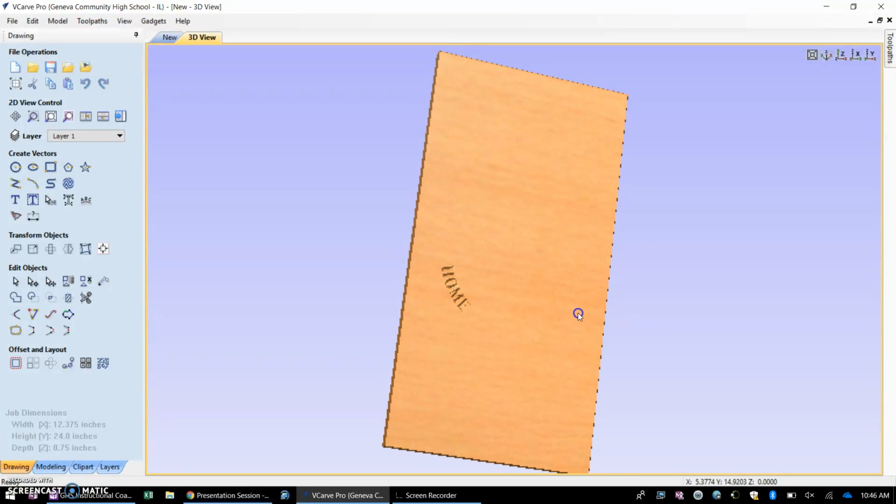Okay, so notice how it's not through because it just doesn't need to cut that deep. If you end up cutting too deep, the software will warn you that you're going to cut too deep. If we cut through the wood and we want to do that on purpose, it'll tell you you're going to cut through. So it'll say put a piece of material that you don't care about underneath as you do it, which is actually what we have over there right now.